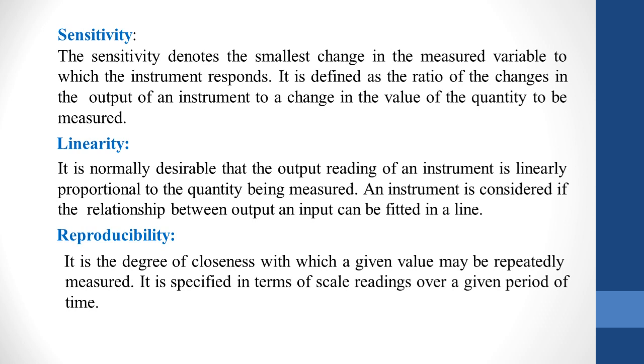multiply by a fixed constant rather than consult a nonlinear calibration curve or compute from nonlinear calibration equations. Also, when the instrument is a part of large data or control system, linear behavior of the part often simplifies the design and analysis of the entire system. Therefore, relationships to the degree of straight line relationships are common. That is, linearity is common.